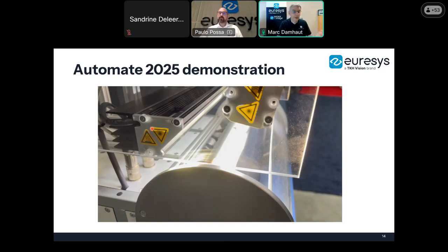And it's super interesting to use bright field and dark field illumination to detect different kinds of defects on the surface of the object. So it's not possible to see in the video, but these two lights are not constantly on. They are being switched on and off alternately in synchronization with the camera.